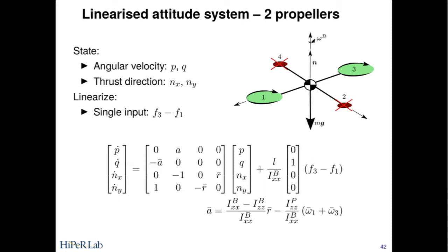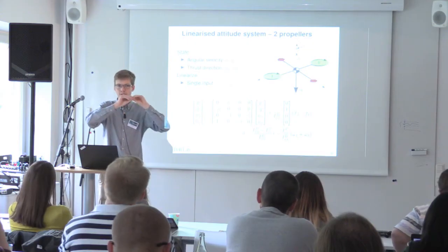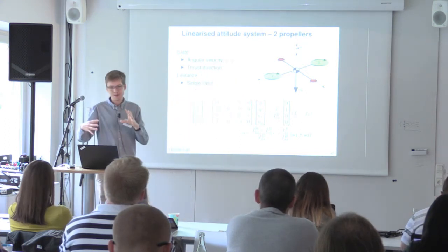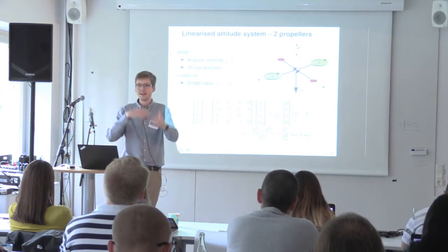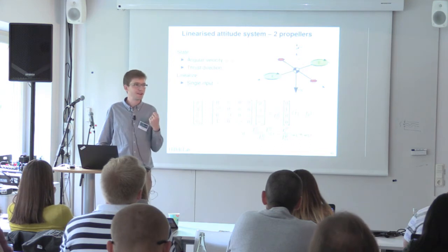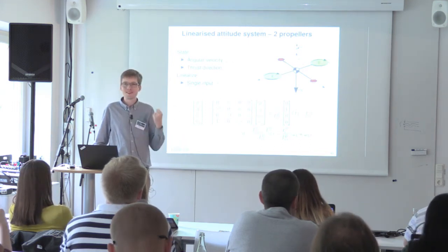It turns out if you build a quadcopter that's very flat, where all the mass is concentrated in a plane, you cannot control it using only two propellers. If you build a quadcopter which is spherical, where the mass is roughly equally distributed around the center of mass, you also cannot control it in this fashion. So this gives us an intuition that if I want to build a system that is capable of operating when I lose some of the propellers, I need to put the mass in a certain configuration. I need a system that's somewhere between a pancake and a ball. But once I have the system that I'm happy with and I have this configuration, it's relatively easy for us to design a controller. And I guess Waleed yesterday showed us how to design a controller for one car to follow the other.